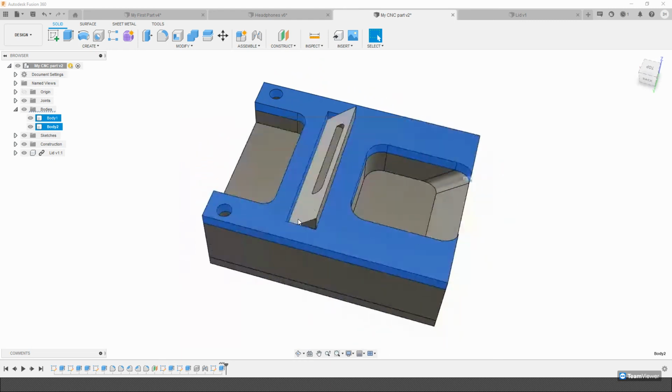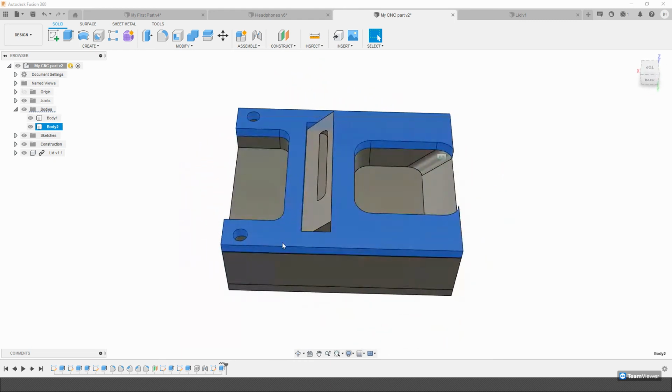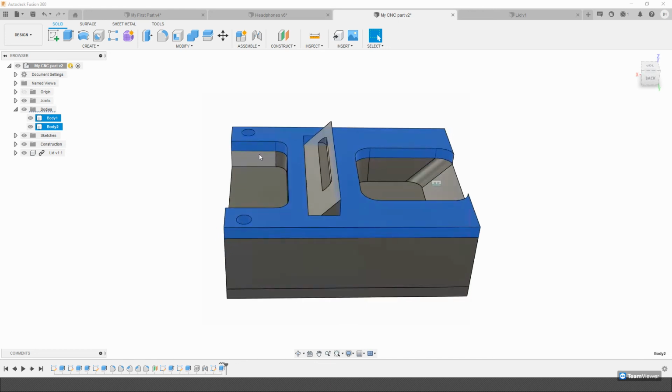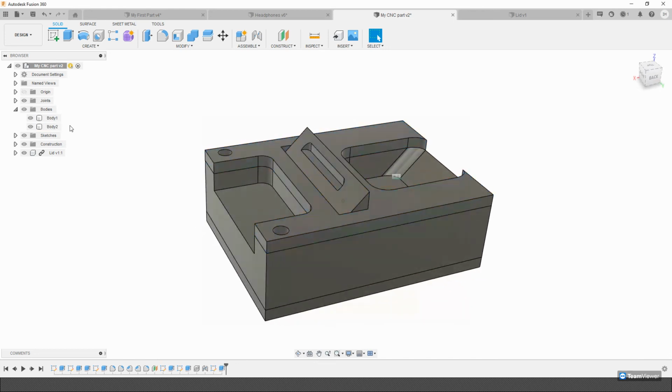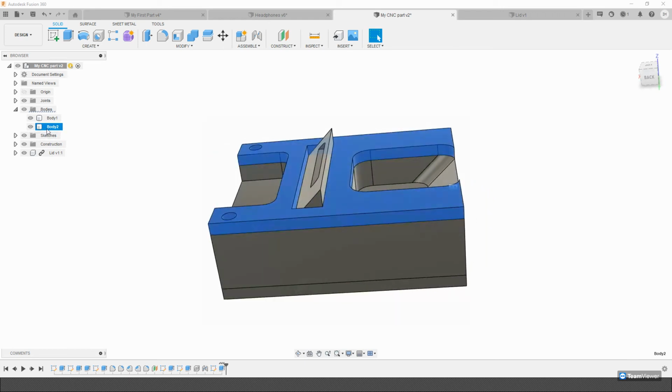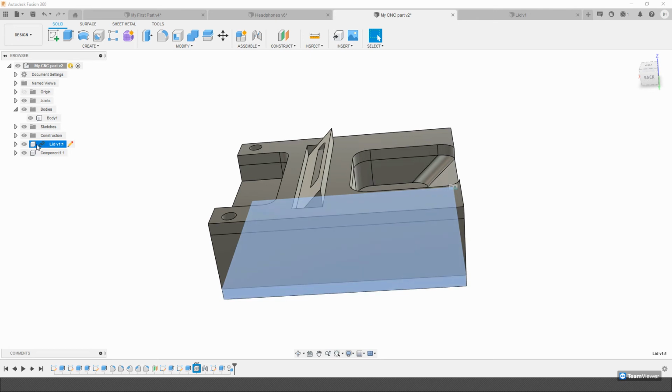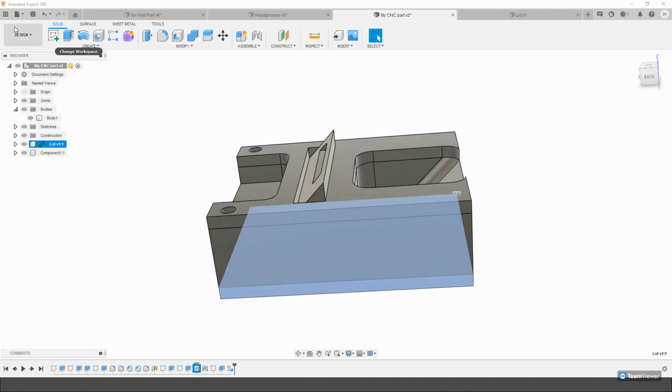And it's quite easy, where I didn't have to go and remember that it was 200 by 150 and remember the size of the holes, because I just based it on the sketch that was here. Now, mind you, it's still not a component yet because it's just a separate body. What I've got to do is right click it and say create components from bodies. And now there it is on the bottom here. It looks just like the other one, minus the little chain link icon.